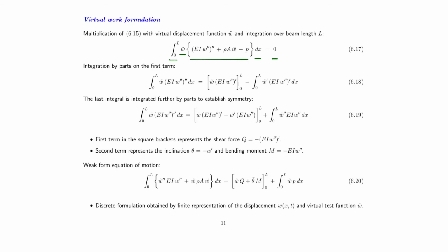We see that the two last terms have the final form. There is no difference in the order of differentiation for the two last terms with respect to the spatial coordinate x, but for the first term we see 4 derivatives on the stiffness term and no derivatives on the test function. So we need special concern for the first term.